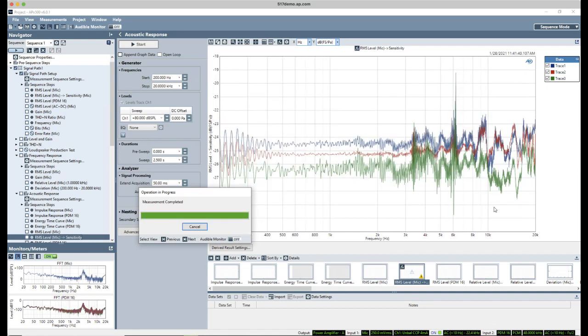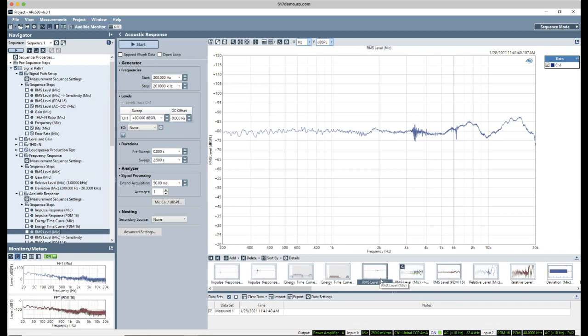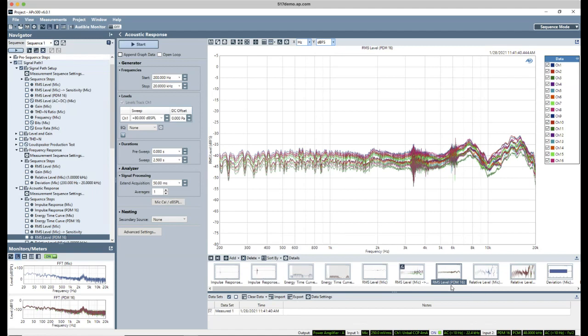And again, the frequency responses, there's still little odd things here that happen because of the behavior of the speaker, but the frequency responses basically come out the same. And that's because by calculating this as a ratio between our reference microphone and our PDM microphones, we are removing or dividing out the source speaker.